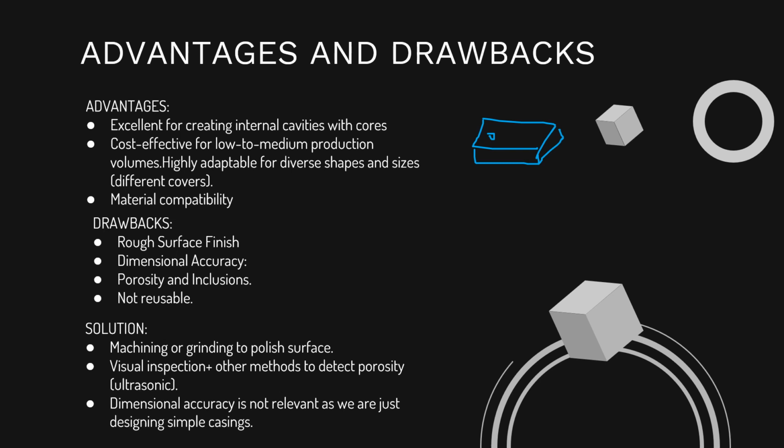Some solutions: for the rough surface, we can perform some machining or grinding in order to polish it. And then against those micro defects, we can perform visual inspection. And for inside defects such as microporosity, we can also perform some ultrasonic tests.